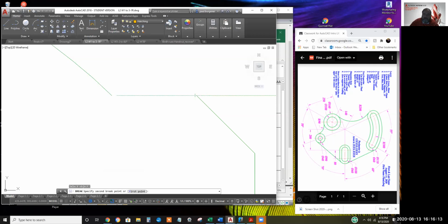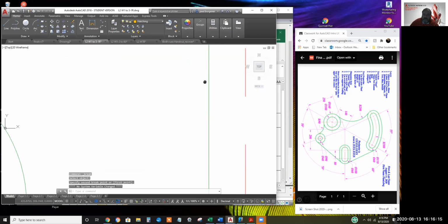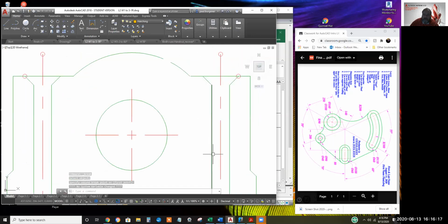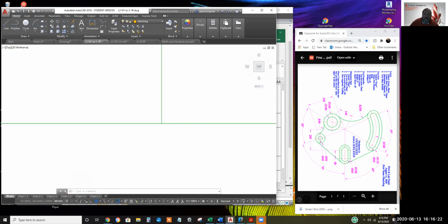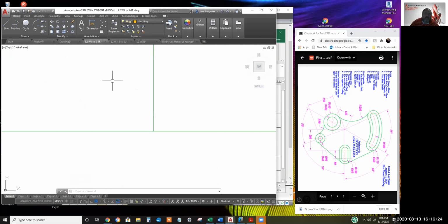So we could use the break command to open every one of the T intersections so that the edit polyline process, probably the closer, the more you zoom in, the less these little gaps will show on the paper.